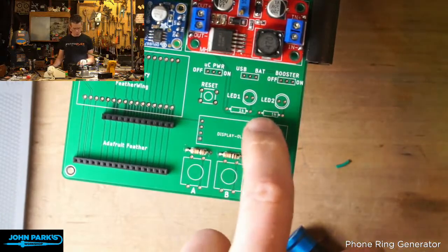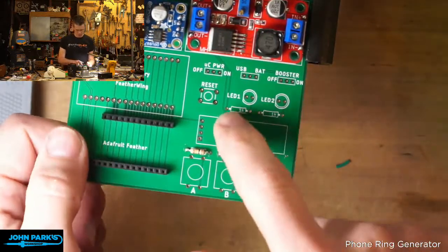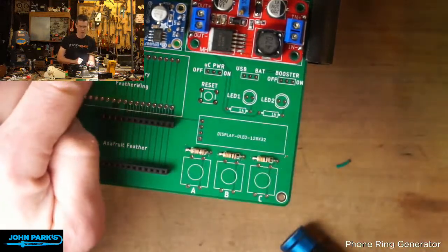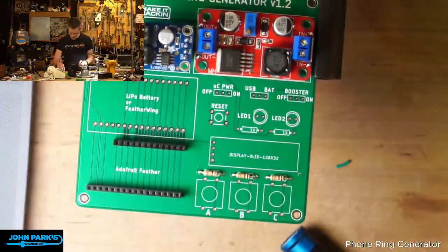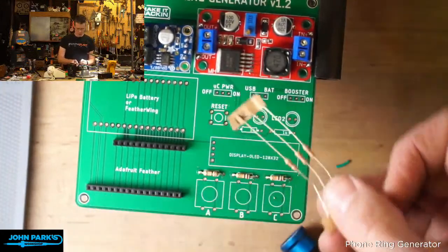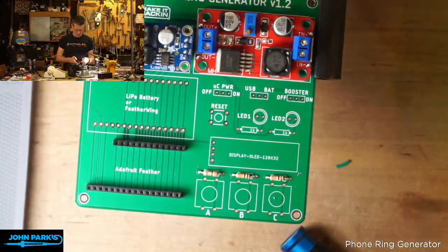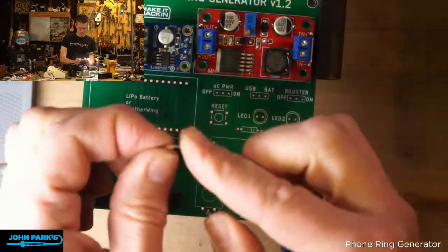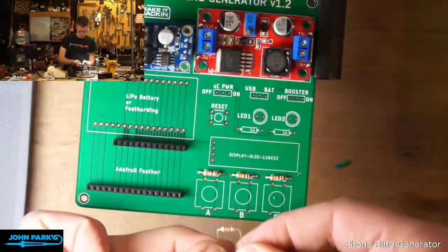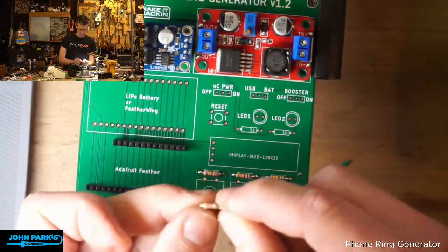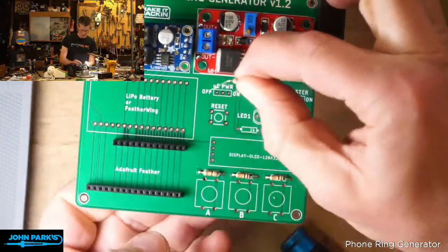And now I'll do these 1Ks here. There's a pair of 1K resistors here. There's also one up here, and these are for LEDs. There's some status LEDs. So here's my 1Ks. I measured them, marked them. Actually, Andrew marked the 10Ks, I think, which makes it pretty clear. The others are the 1K because there's only 2 values of these. Okay, so let's keep our tolerance band to the left for this build.